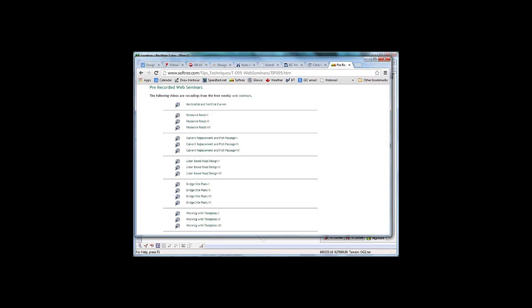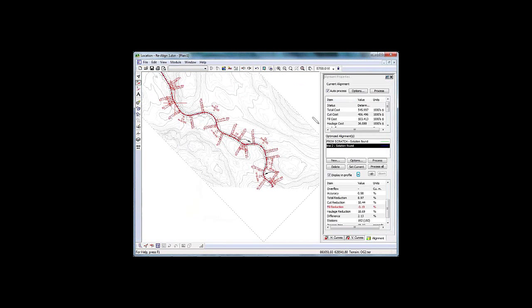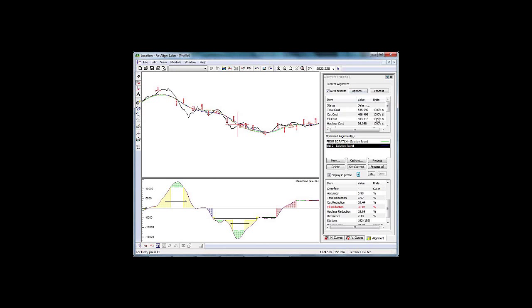Tyler is asking me for a second opinion after you've manually created a design. Yeah, okay. He's pointing out, I think, Tyler, that once you've created a vertical alignment, you can just use the optimizer to find for you an alternate vertical alignment and immediately compare costs. It always comes out cheaper. That's the whole point of optimization. And if you put in the correct control points, the optimized solution should be better than the manually designed one.